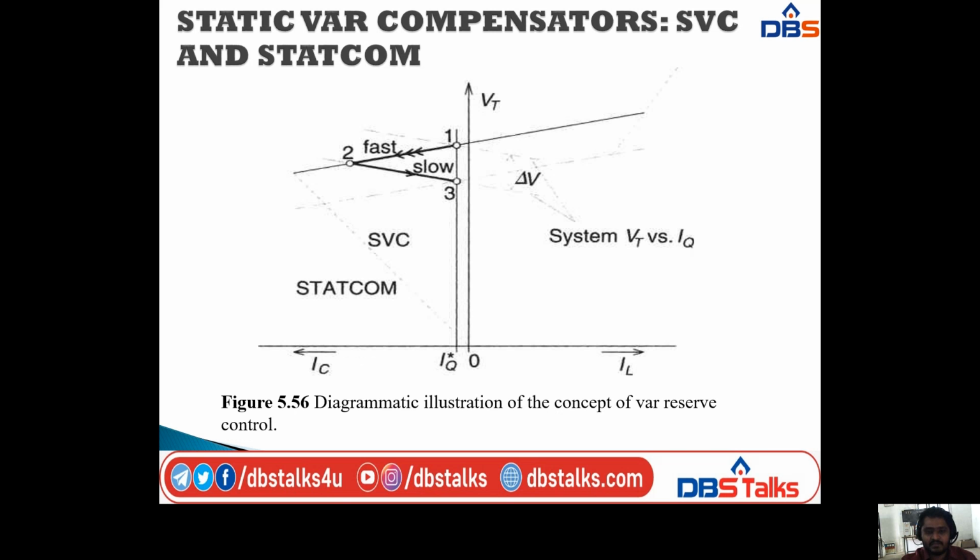If you observe this diagram, here I will draw the diagram between IC, that is current, versus voltage. That voltage is the terminal voltage and the current is the inductor current and at the same time the capacitor current. Here I am considering the midpoint, and at the midpoint I am drawing a vertical line, that is the VT line. Next we have two responses, one is slow and one is fast. I am taking 3 points here, 1, 2, 3, for SVC and STATCOM.